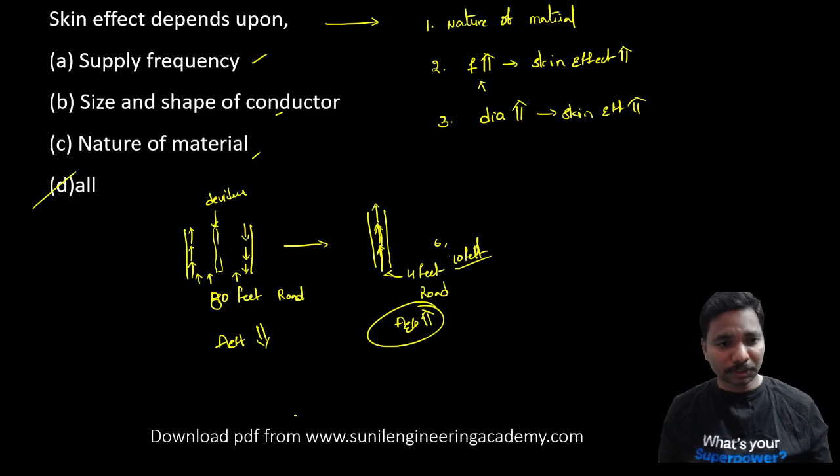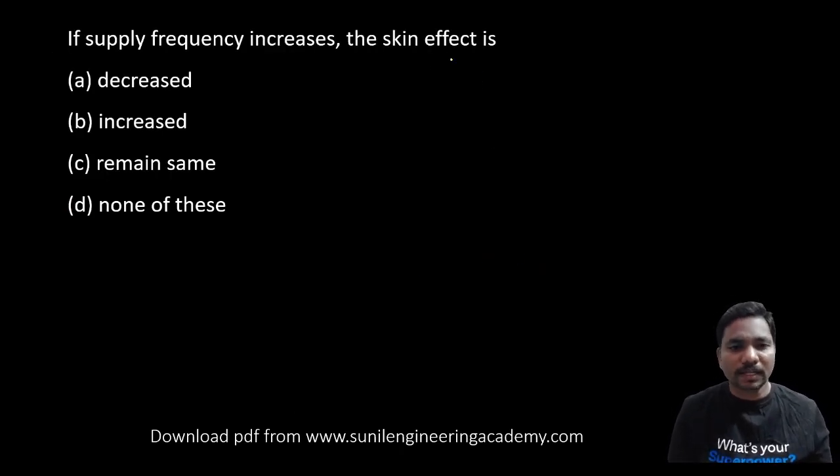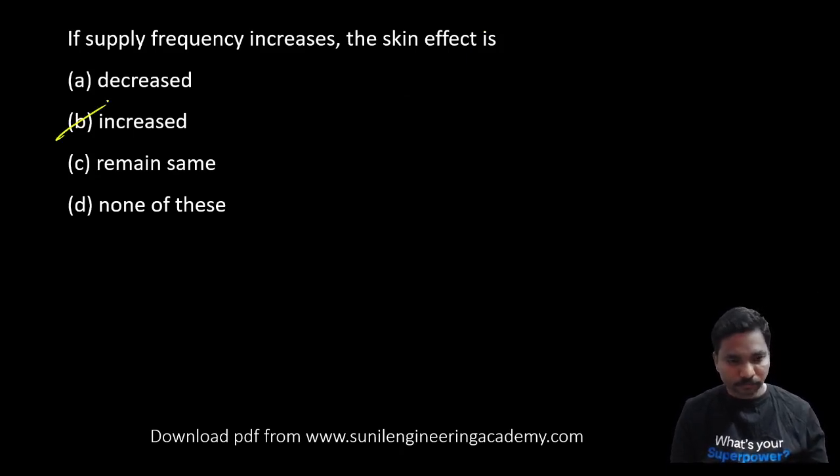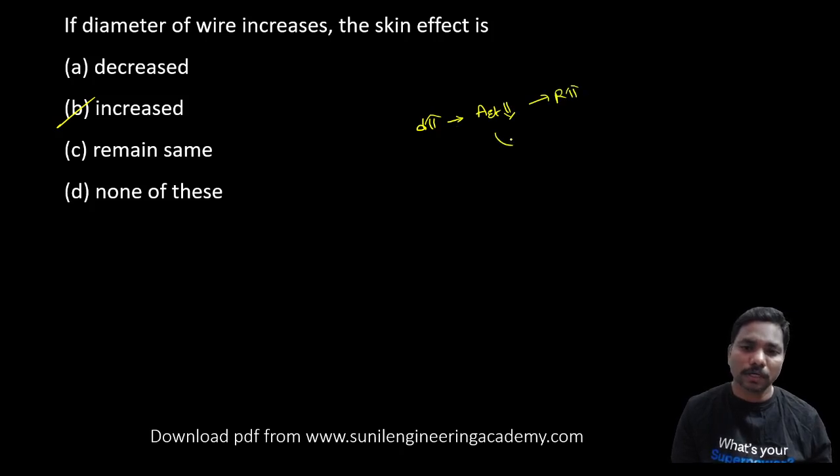So we can go with that option as the answer. If the frequency increases, skin effect increases, as already given. Coming to the next one: if the diameter increases, skin effect also increases. If the diameter increases, then effective area is reduced, so resistance is more and skin effect also.